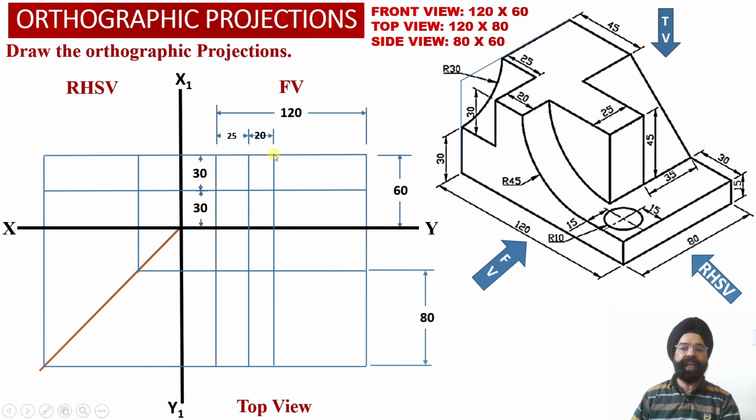Now having obtained this point, we know that this distance happens to be 45 millimeter. That is, this vertical web which is our element number 3 has width equal to 45 millimeter corresponding to the top surface of the solid, and it has height equal to 45 millimeter, measured perpendicular to the base of the solid.